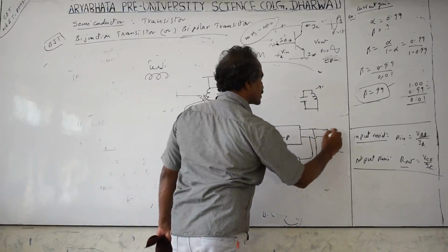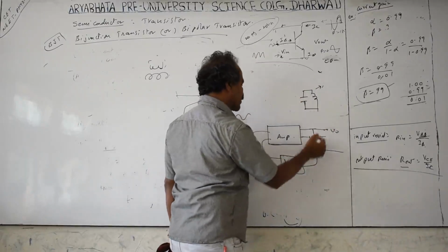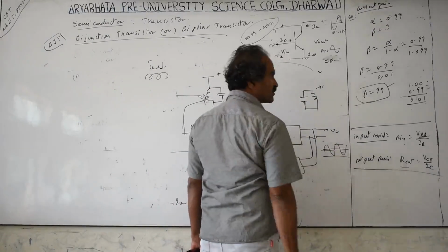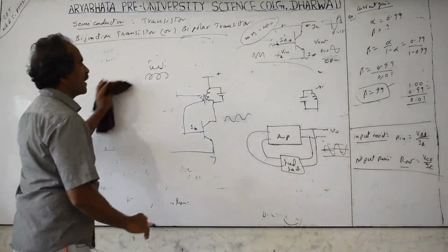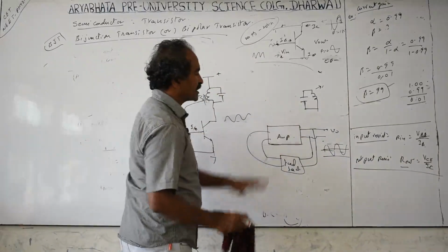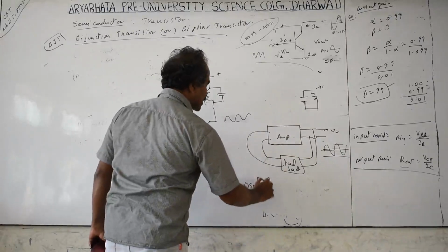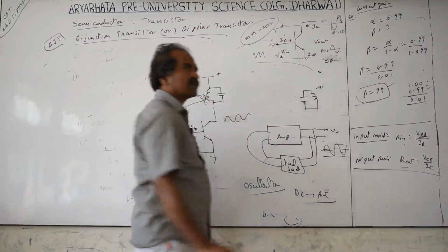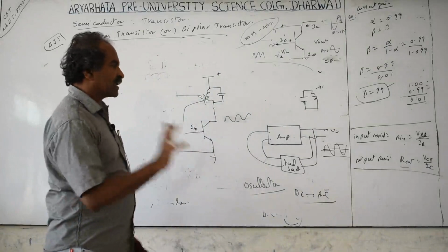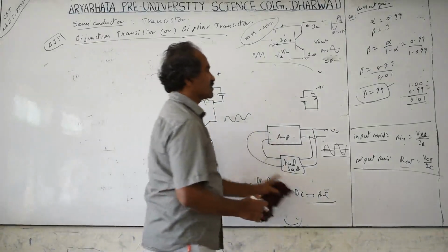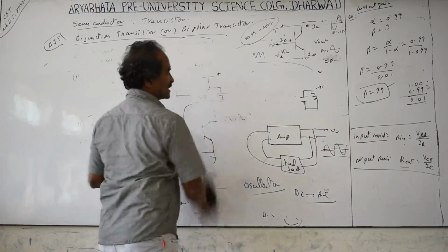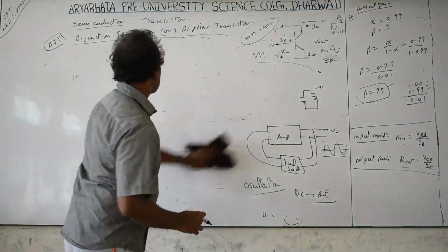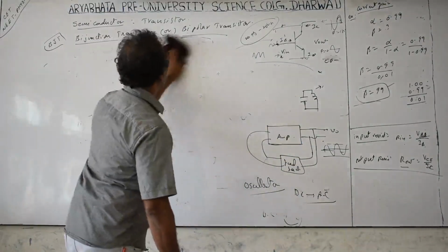So whenever in this case the signal is decreasing, for this amplifier we take the output from the collector, capacitor and inductor. Now this is a transistor amplifier. A small amount of the output is taken as the input for the base. This comes as the base current IB. The output current, which is decreasing, is taken as input and given to the base. Again the base is biased with the help of the resistors. So this signal coming here will be amplified again as output. So output will be continuously coming out. This is called the oscillator.